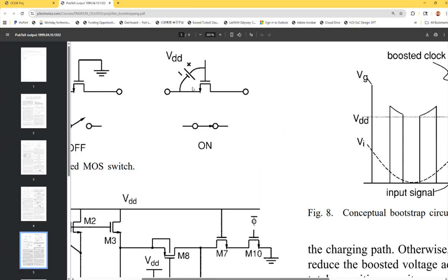But how could this give you a constant VGS? Because that's a voltage source. You cannot change the voltage source. It's an ideal source, right? If I tie here and there with the VDD, VGS will be VDD all the time. So what if you have a signal coming from one point here? What's going to happen? Are you able to pass it to the other side? Won't it add with VDD? Yeah, it's going to add to VDD, right? And then where to add? Which one will add a VDD to it? The source voltage. Yeah, the source voltage.